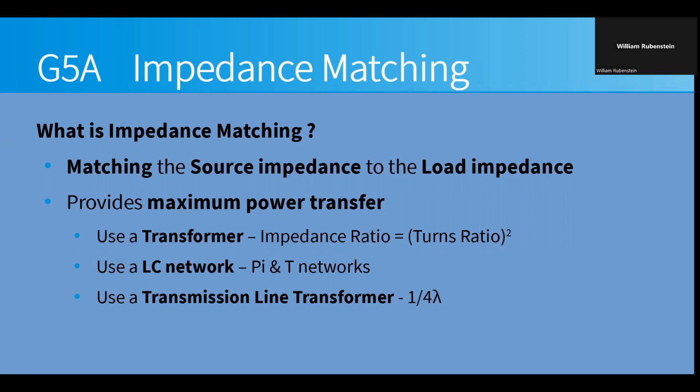Now, because that rarely happens, you have to have some way to match those impedances. You're kind of stuck with 50 ohms on the transmitter. You can play some with the antenna, like on a dipole. If you start dropping the elements, it will lower the impedance. It was normally about 72 ohms, and you can get it down in the 50 or below range, depending on the angle.